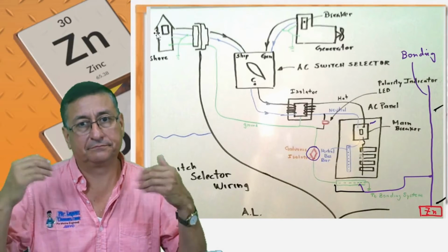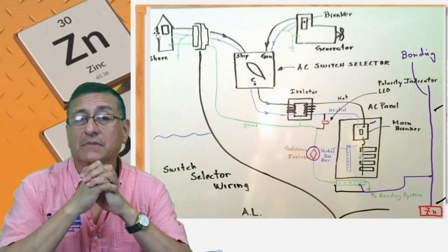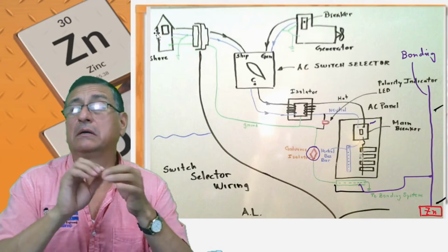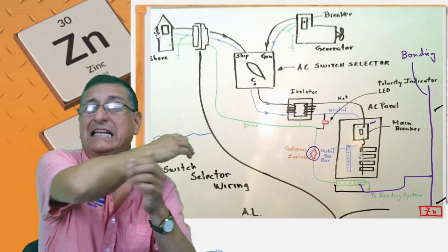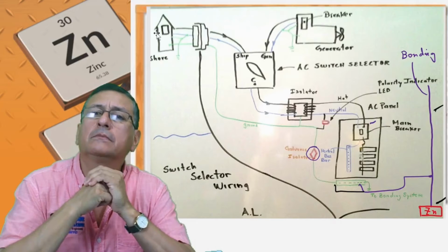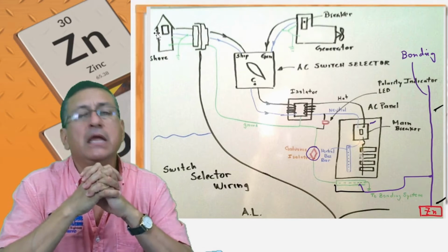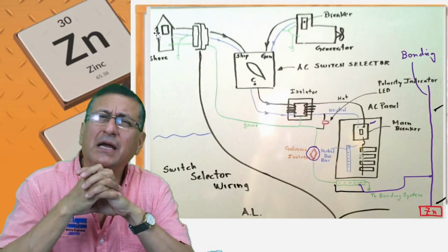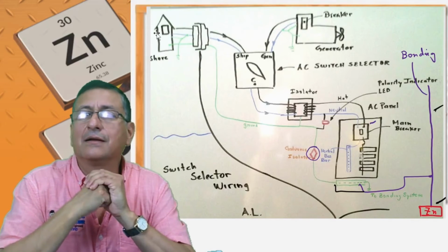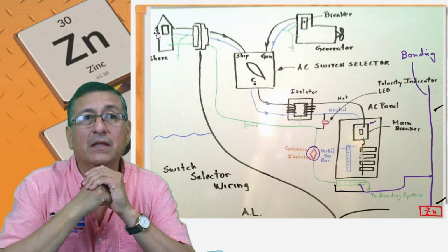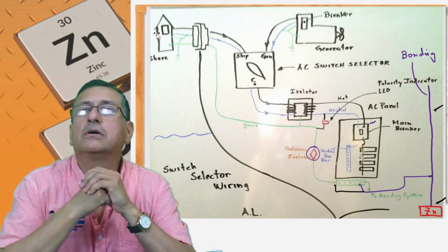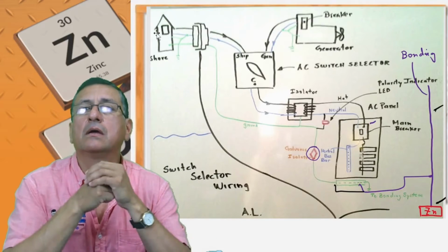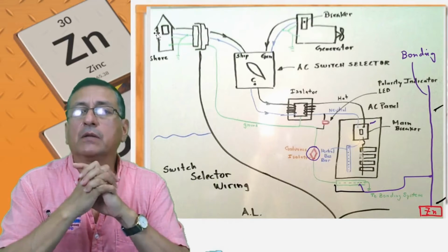The through holes in permanent contact with salt water, with a high current flowing through them, pitting corrosion is accelerated and perforates those through holes easily. I remember that situation in a boat some years ago in Fort Lauderdale. I think the name of that boat was Taka Taka. That boat was docked in the marina in Roscioli. And in that boat, reverse polarity, wrong connection, produced that situation, and the boat sank. The water penetrated. I remember that boat.